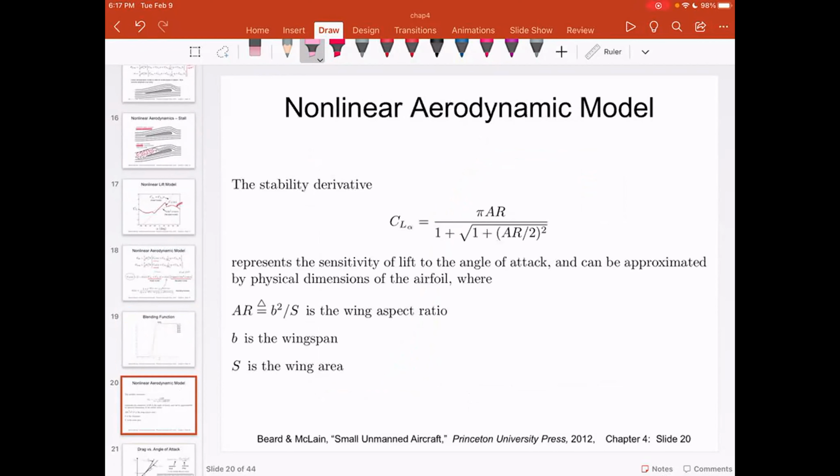Now, this is something interesting. The stability derivative. What is the point of using these equations? Okay, the equations are used because you cannot do wind tunnel testing for fractions of angle of attack. Usually what you will do is you will have a standard airfoil like a NACA airfoil. And you will perform the wind tunnel testing at 5 degrees angle of attack, 10 degrees, 15 degrees. Now you want to find out what happens in between. What would be the forces in between?